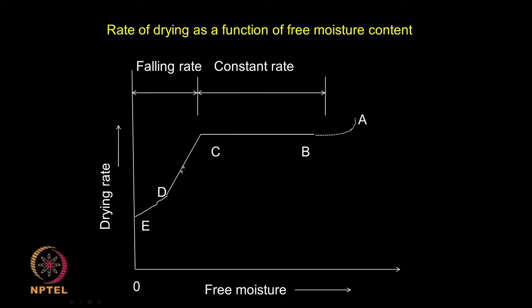Okay. So, when you are drying material, initially the moisture is so much that at a constant rate the moisture is removed, that is called the constant rate drying. Once the moisture amount goes down, moisture is present only inside the capillaries. So, the water has to come up to the surface, and then it has to get evaporated. So, the drying rate goes down. So, here the controlling factor is how the water diffuses out from the capillary to the outside.